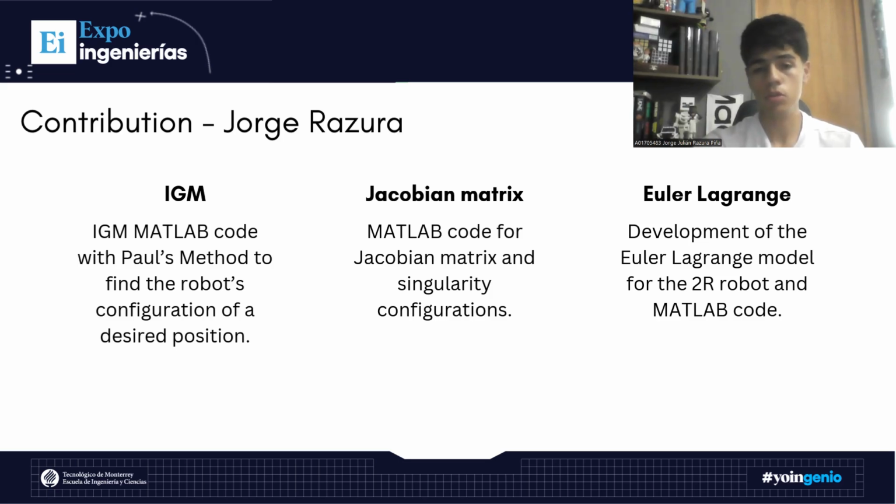My individual contribution was to find the inverse geometric model of the robot with the Pieper method, to find the Jacobian matrix and the singularity configurations of the robot, and also the development of the Euler-Lagrange model.